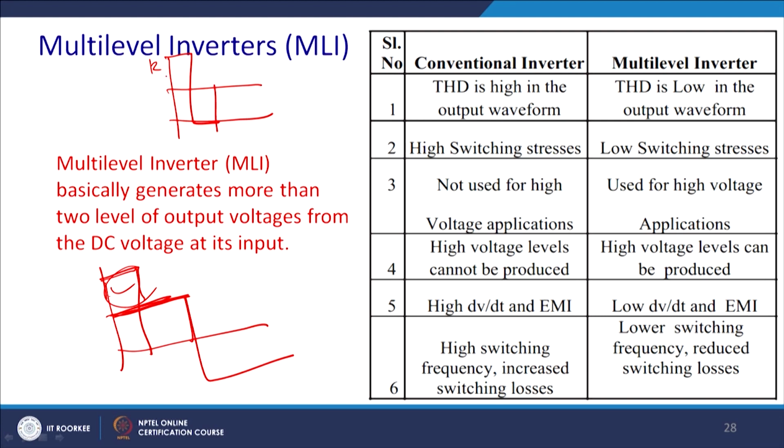Okay, theoretically it is okay, but what happens is the power quality decreases. You require a sinusoidal voltage, and once you switch on, when you have almost 0 voltage, you are applying the whole DC voltage. Then you say that the volt area matches, but within that area it is filled up by unnecessary harmonics.